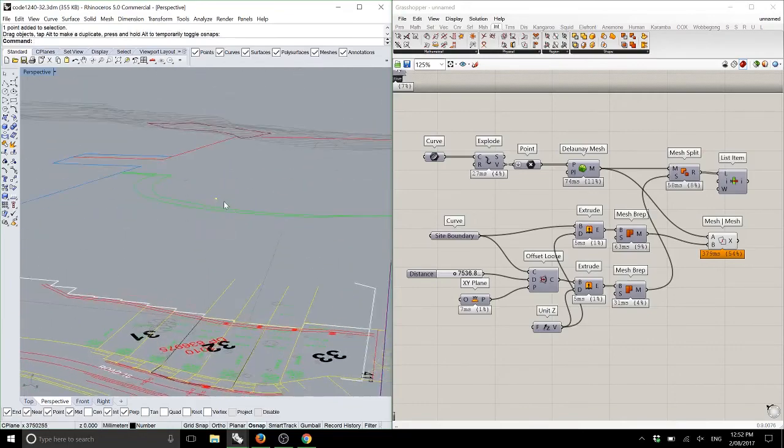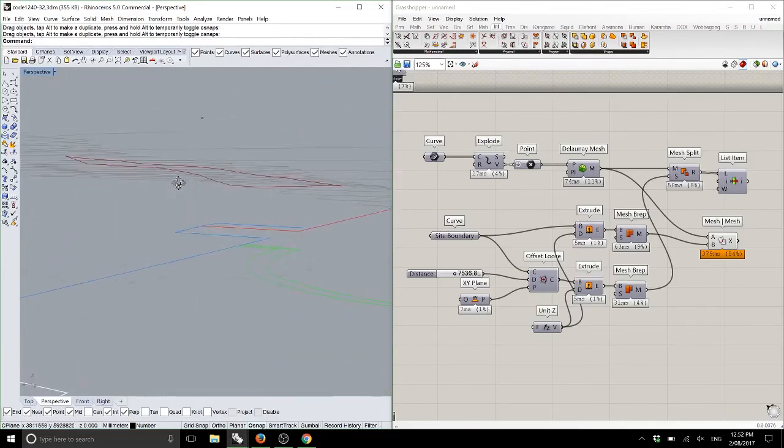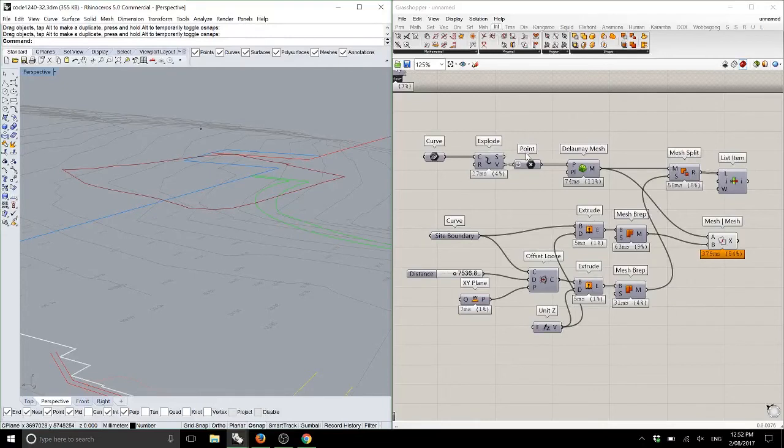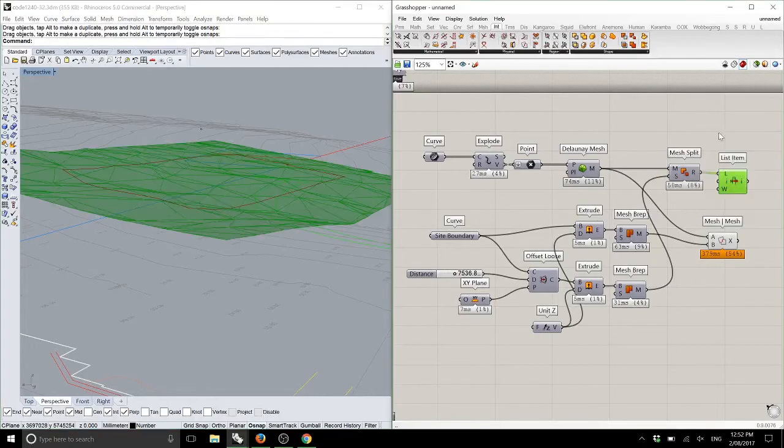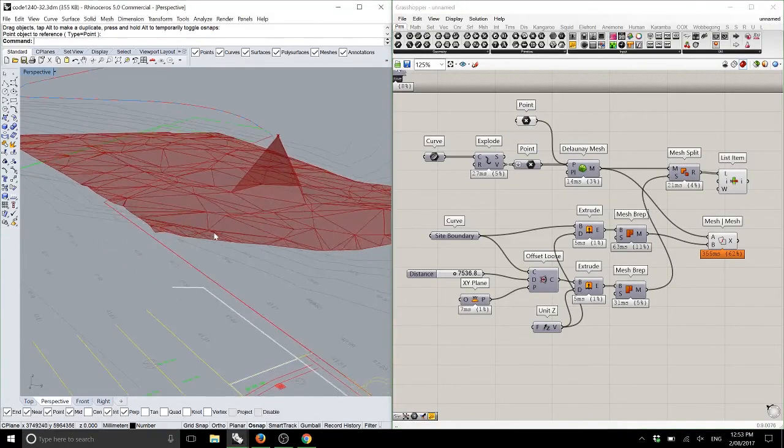I'm just holding control right now, which allows you to move things vertically in Rhino space. So that point there floating in space, all it has to do is move into that Delaunay system and it will affect it. So if I pull this up again, I grab that point. I right click, set one point, select that point, hold shift and pull that into the Delaunay mesh. We can now start affecting the site, okay? So it's just as easy to remove points from your contours. Cool? Great.